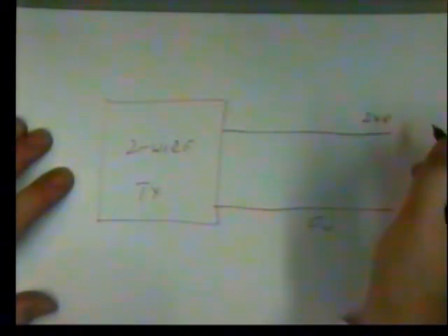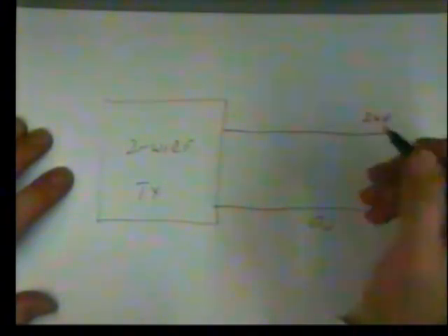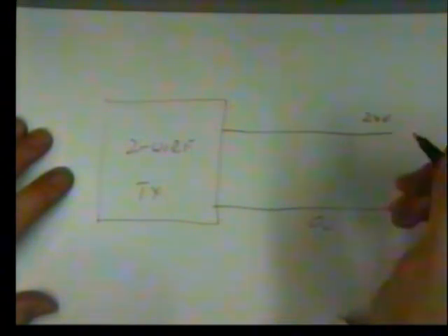That is a standard factory power supply. That's why we've had to cover things like relays, which are used to switch 24 volt supplies using just a 5 volt computer signal. This is quite an important concept because most factories are wired up with 24 volts, not 5 volts. And 5 volts is the computer level, whereas 24 volts is a factory level and also what's used in cars. So how do we modulate information on the 24 volts?